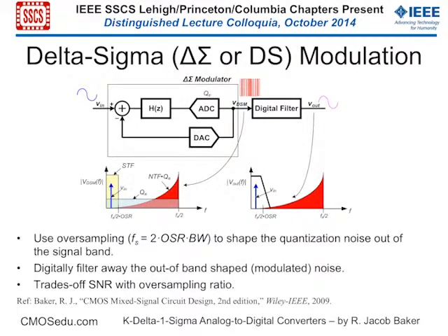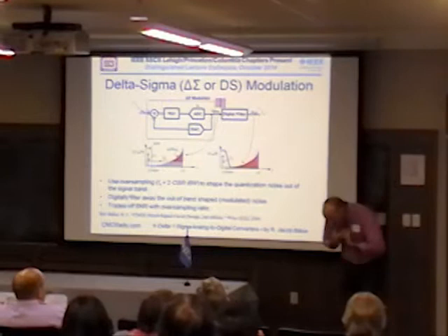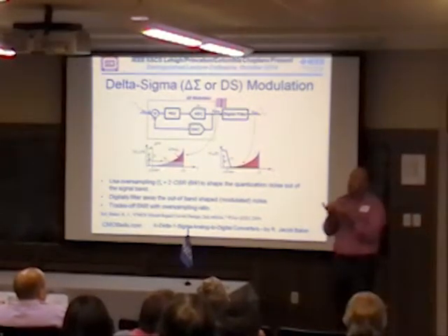Okay, so let me pause here before I go on any further, and I just want to make sure everybody knows what a Delta-Sigma is, because that's a kind of a weird name for a very simple concept. So I want you to imagine that you're trying to measure some water going into a bucket. The bucket corresponds to the sigma in the Delta-Sigma. Every 10 seconds you're going to look at the bucket and decide, is it above or below some arbitrary line?